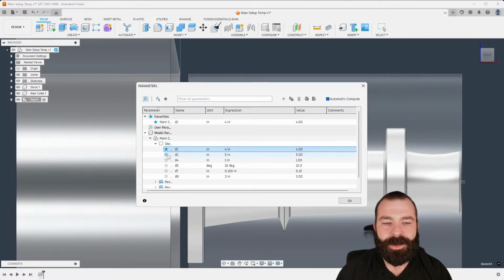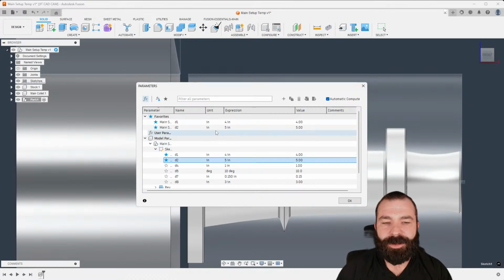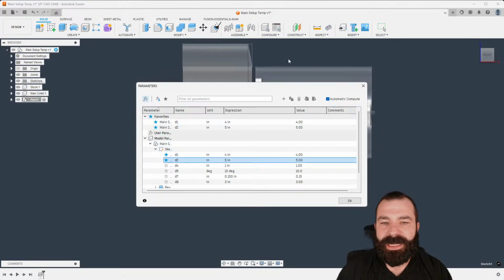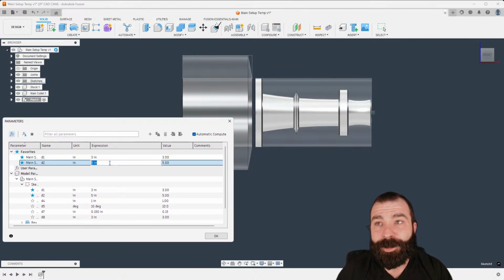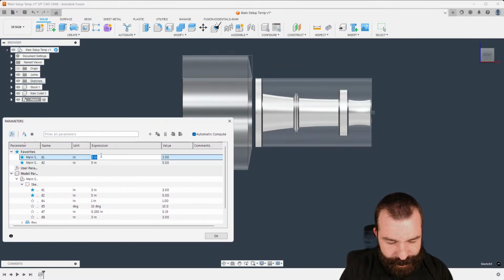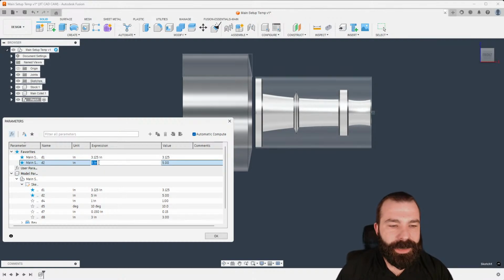And if you remember, we have an OD and a length, right? We can relabel these at any time. But as you guys are seeing, we may actually want to go to a 3-inch stock. I can't remember what size I drew this part at, but let's go 3.125. And then from our length, we're going to have to saw cut that possibly at 5.125.